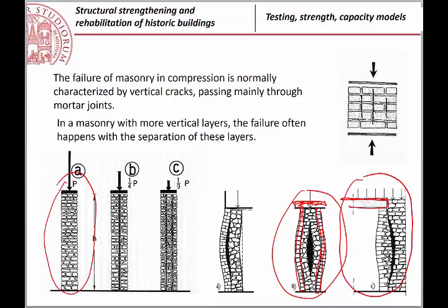You see from here that if the slab is supported just over the first 20-30 centimeters of a wall, you are not distributing the loading in the wall thickness layer. You are able to only if the 2 parts of the masonry are connected. So connections are very, very, very important.